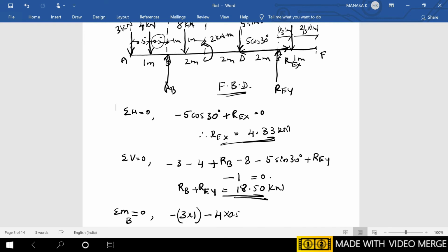Next, you go for the load present here, 8 kilonewton, that is downwards. It is acting downwards with the intensity 8 kilonewton and a perpendicular distance. Imagine the line of action is like this. Point to be considered is this one. From this point, drop the perpendicular. So this will be the perpendicular distance, which is equal to 1 meter. Next, this is downwards. For B, it will twist or rotate in this manner. So it is now clockwise. So it will be positive 8 into 1.